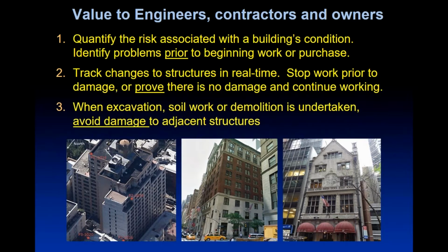Foundations, that's a complex question in New York City, but our accelerometers are triaxial. So what we are looking at is both the X and the Y direction and the vertical. Now, the vertical response, dynamic response of the structure is a function of effectively the building sitting on a spring.